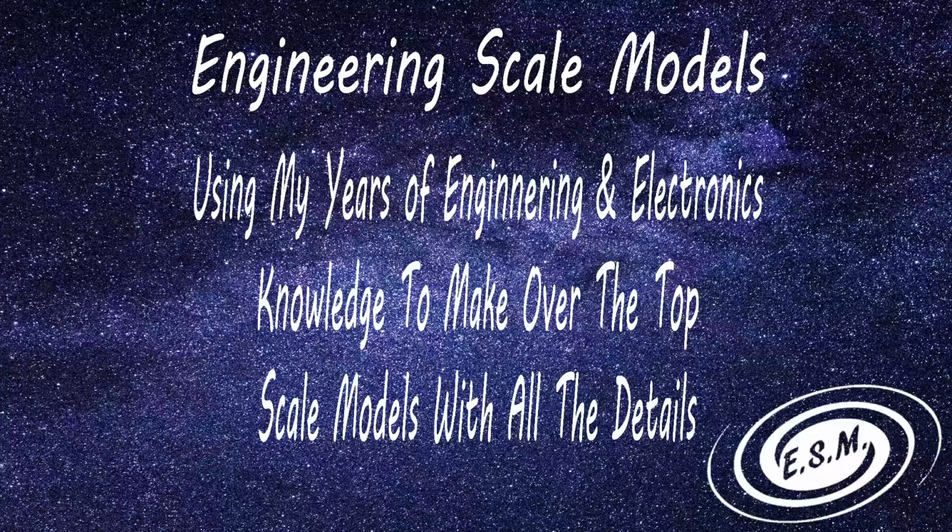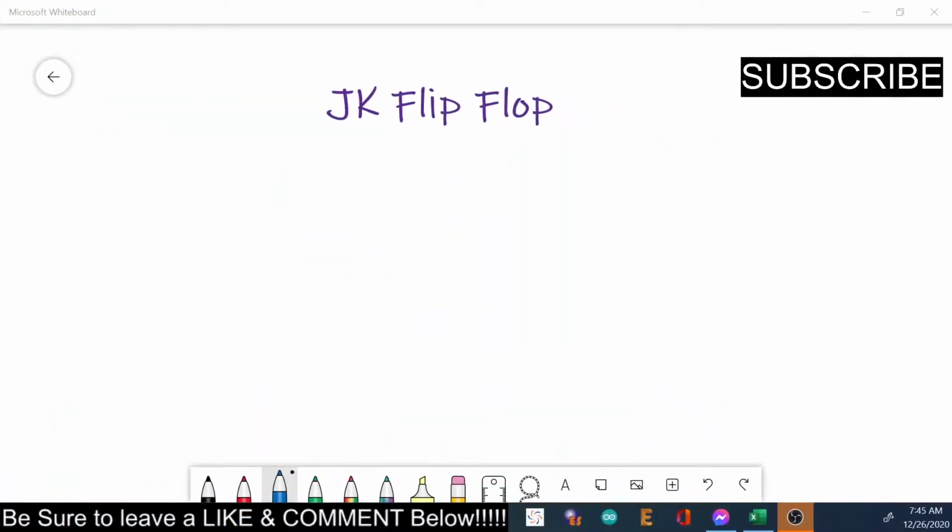This is going to be a purely academic video on basic electronics with the logic series, and this is going to be about the JK flip-flop. Now, your JK flip-flop has a basic block diagram of you have this, and then you have an input here, and you have a clock input. Then you have two outputs, your Q output and your Q inverted output, Q naught, and then you have your K and your J, and then you have your clock input.